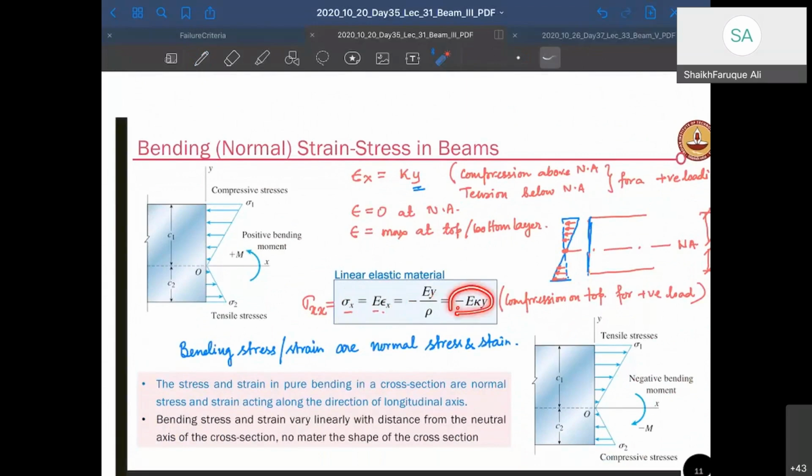That's your stress. So now the stress is also a linear function of y. It's like strain. So strain is this, and the stress will also be something like that. Some books will draw it like this, but be careful with the arrows. The arrows in this direction represent tension, and the arrows in this direction represent compression on the member. Other than that, you can draw it this way, or take another line here and draw it like this. It's up to you, but be careful with the arrows. Okay, so far so good.